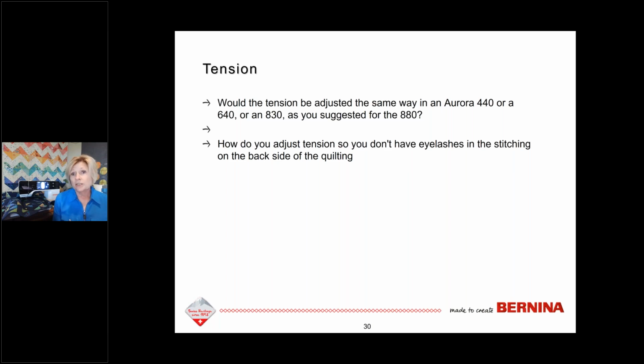I'd also check the lower tension, see where that's at. I don't remember if you said what machine you're using, but try the different bobbin cases and see if that helps. From there, I would check the needle, see if you have a burr on your needle, or a burr on your needle plate or somewhere internally with the hook system that would be catching on that thread as it's stitching. That one's hard to diagnose without seeing, but those are the things I would check.